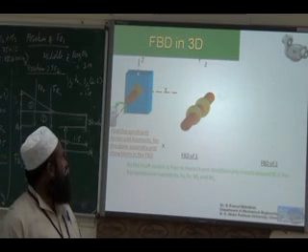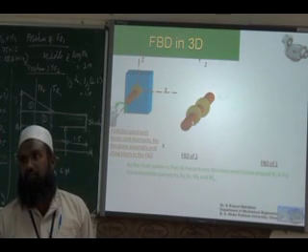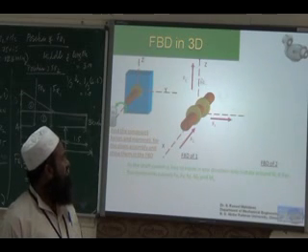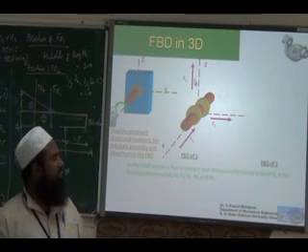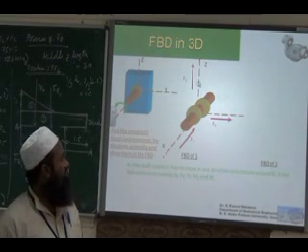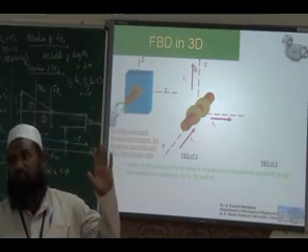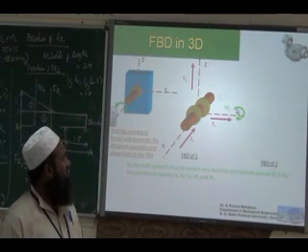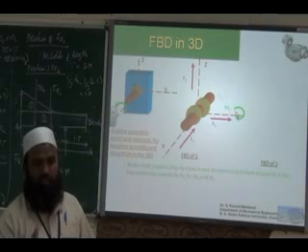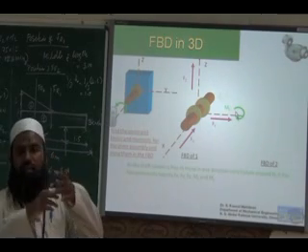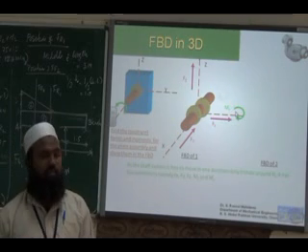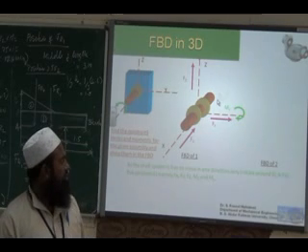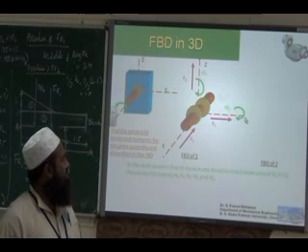If you draw the free body diagram for the first part, the shaft and collar, the first integral part, with the 3 axes: no translation in x, y and z, so reactive forces are developed. The sense of the forces is arbitrarily given. It need not be upward or downward. There is a reactive moment about Y; it cannot rotate like this. The bearing will restrict rotation of the shaft around Y. It cannot rotate around Z also. It can rotate only about X. So we will have two reactive moments.